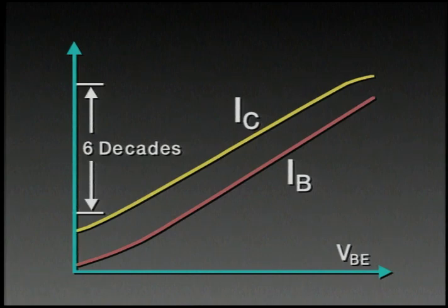I'd like to suggest that you forget everything you've been taught about transistors as current-controlled current sources. That is, the presence of the base current is inevitable and it's unavoidable. We need to deal with it in a practical design, but it's not germane to the concept of transistor behavior, in my view, or at least in the translinear view. Really, the best way to view the transistor, at least for the purposes of this discussion, is as a voltage-controlled current source.